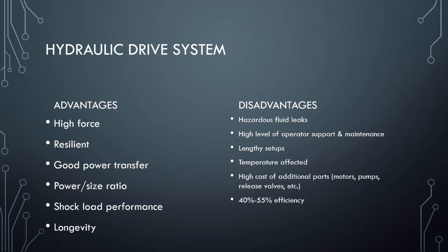If you need any additional parts for these systems, if you wear out a motor, you need a new pump, release valve, anything that's going on these units, those are going to be a lot more expensive than anything needed for a pneumatic drive system or an electronic drive system. Those components can be a lot cheaper to replace, whereas a hydraulic system starts to get really pricey. So the cost of replacement parts and of maintenance in general on these drive systems can be really high.